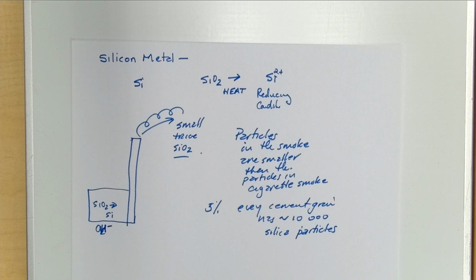When we first started using silica fume in transportation structures, we were using 12 and 15%, probably because we hated the finisher. And in the lab, you got great, fantastic concrete. Very dense, water won't go through it, lots of good things. Except it cracked every 6 inches in each direction. So in between the cracks, it was really dense, but it didn't matter because the cracks were too tight together. So we used 4, 5, 6%, 3%.